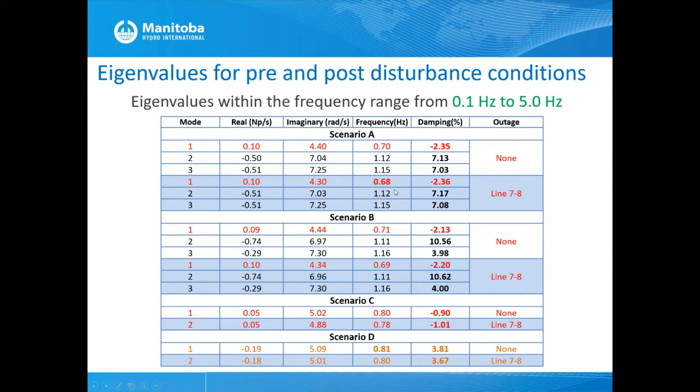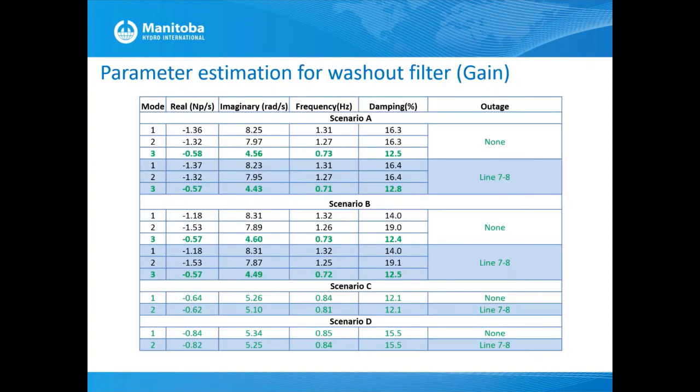And in a later slide, you can see the damping of all these modes has been increased. In this slide, we can see the modes still have very similar frequency levels, but the damping of all of them has been increased. So the objective was to increase damping from negative values to sufficiently positive values for these 0.7 hertz modes.